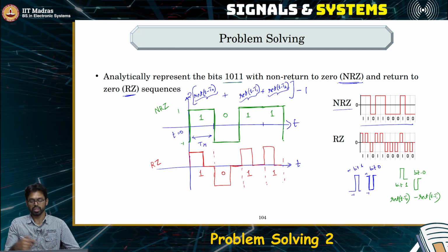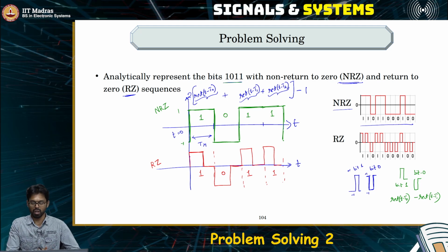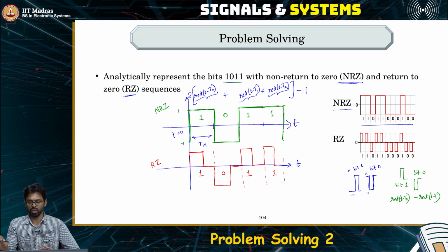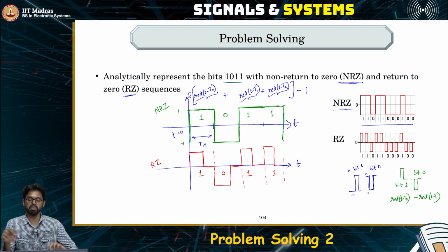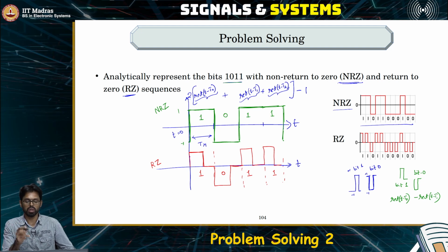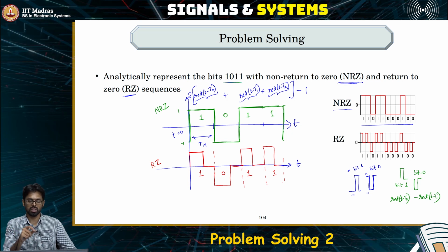These are actually used in wired communication signals. So if you cut open, let's say, a USB cable and connect it to an oscilloscope, you will see something like this. You will see rectangular pulses, and from the oscilloscope you can in fact know what bit is being transmitted at what time if you can zoom in enough and see what the rectangular pulse is.